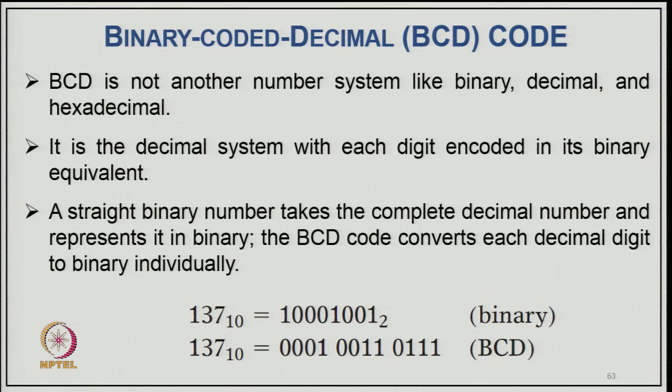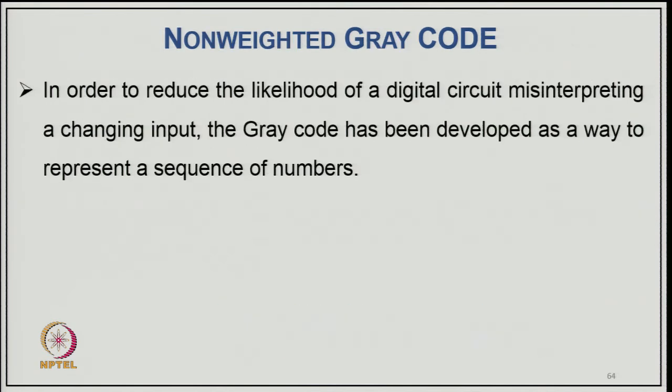dividing by 2, which we discussed earlier, and then 137 in BCD, if we convert it, this is much different because 7 is converted to 4 digits, then 3 also 4 digits and 1 is also 4 digits. So, these two are different. I mean this is binary, this is BCD. So, you can see these are not the same in both. I mean 137 represented as binary is different, and decimal to binary we just took in the same method as you write 137 by 2. So, it becomes 1 remainder. So, it remains 65, then like that we go on converting, which we discussed earlier.